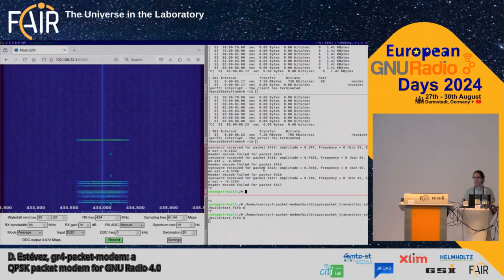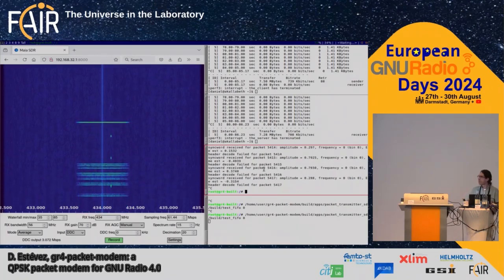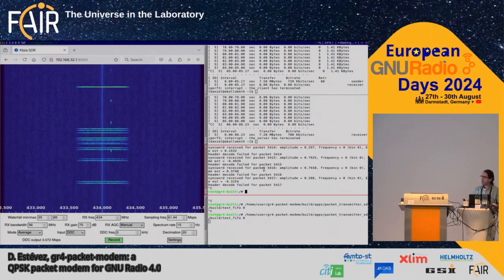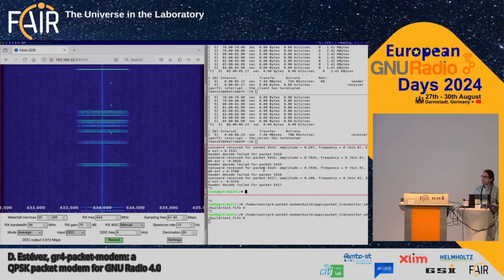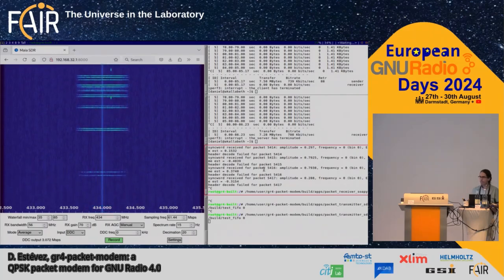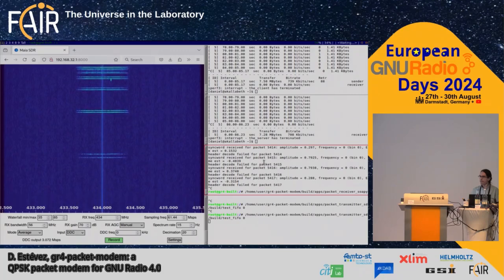Daniel, yeah. Hi. Can I ask something? That's great work, by the way. I'm just curious if you can start iPerf transmission again and adjust the receiver gain while the packet is coming to see how much it can compensate for amplitude variation. Because I understand you didn't use any automatic gain controller or whatsoever, so it may disrupt the Costas loop. Good point.